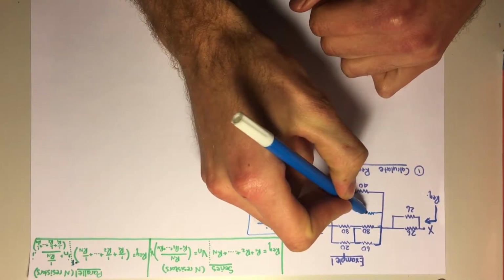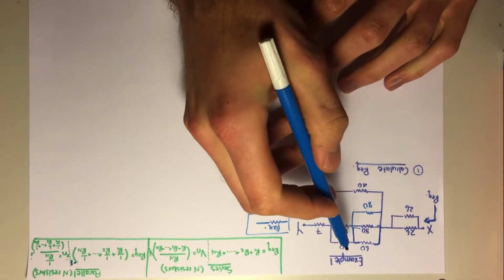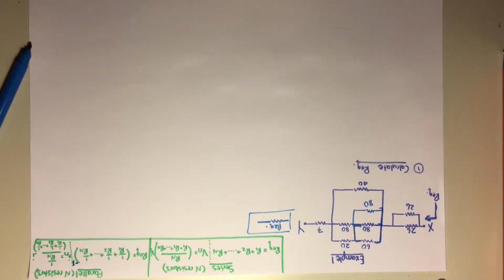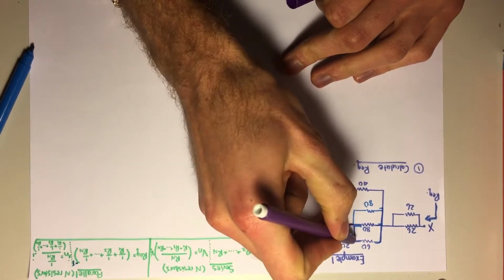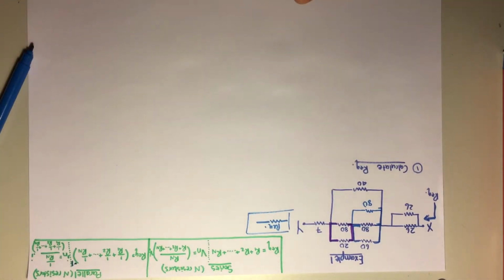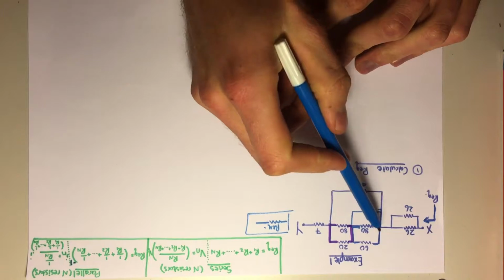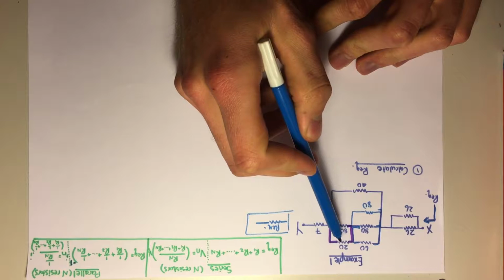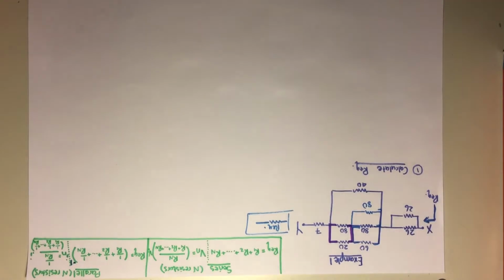And let's just add in an extra resistor here to add some trickery to it. And we can see therefore that these three are parallel. And we can also see that the 20 and the 80 are in parallel at this stage. So what we're going to do is work from the inside out, because we have to work out these, and then only can we consider the resistors outside of this area. Otherwise we're not going to have an equivalent resistance here. We're not going to be able to add anything. It just makes it a lot simpler.